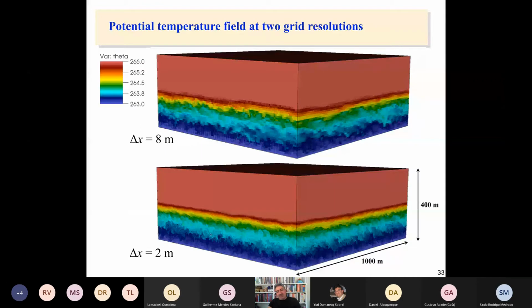So the way grid convergence works is that everything is at the right place. The yellow on the top is where the yellow at the bottom is, and all the colors are the same. If you increase the resolution, nothing changes. You're just getting finer and finer scales in the LES. It's basically like switching from a standard definition television to a high definition version or a 4K. The programming stays the same, and you are just able to see more details.